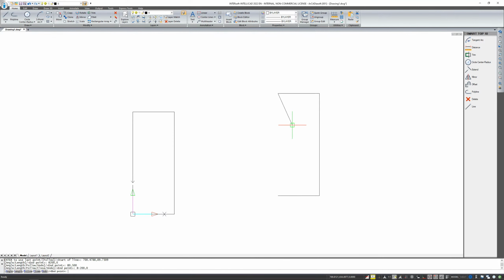And here I can also use an ending or entering the coordinates. But when entering the coordinates, remember that this is the beginning of the coordinate system. So I would have to enter 0, comma, minus 500 and confirm with enter.